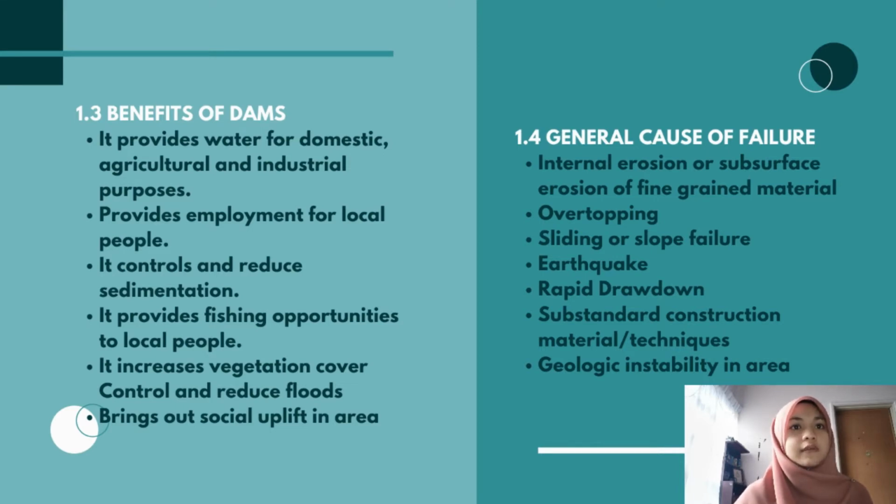And the general cause of failure in constructing the dams is internal erosion or subsurface erosion of fine-grained material, overtopping, sliding or slope failure, earthquake, rapid drawdown, substandard construction material techniques, and geologic instability in area.